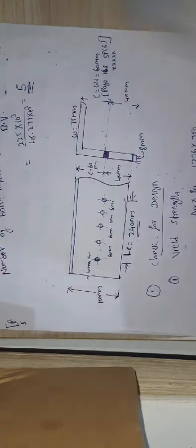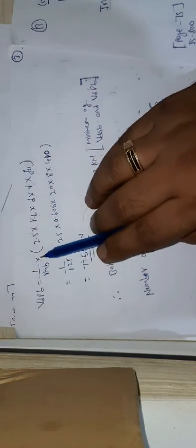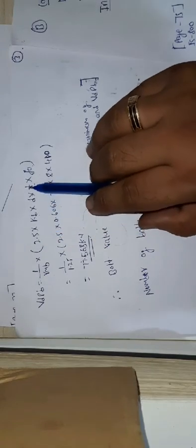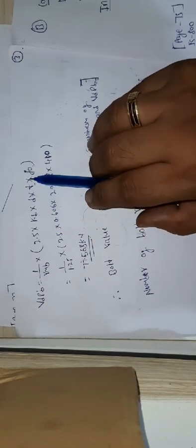Here you can see this is the strength of the bolt in bearing. So we have the formula: VDPB equals 1 by gamma MB into 2.5 times KB into D into T into Fu. So here K is some constant we need to calculate.